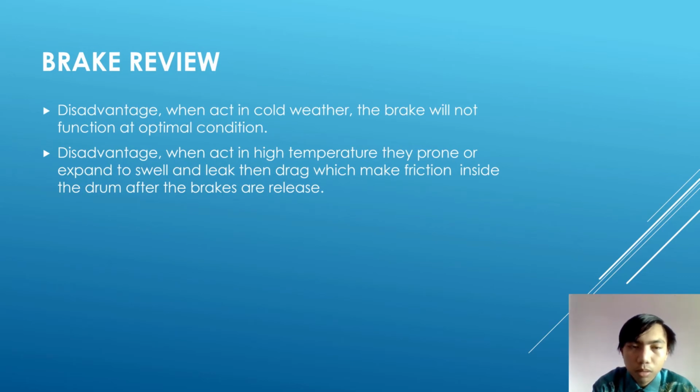Review from its disadvantages. I found that there are two disadvantages. First, when operating in cold weather, the brake will not function at optimal condition. Second, when operating in high temperature, they are prone to expand, swell and leak, and then drag, which makes friction inside the drum after the brakes are released.